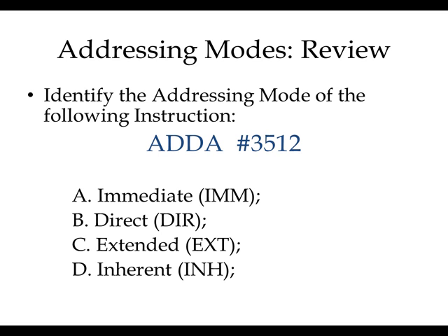Look at the instruction, the blue one. What is the mode? Everybody, B is direct? No? It must be immediate because it has the pound sign, the hash. That's the only one. So the right answer is immediate. Any doubt? Let's look at the next question.